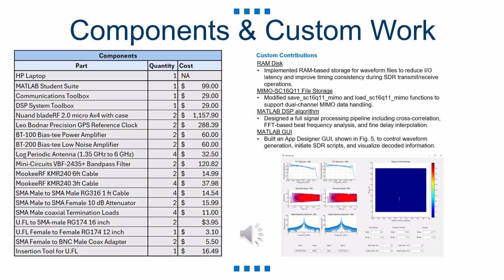The key contributions include the implementation of the RAM disk to store waveform files, which improved latency issues. I adapted the SC16Q11 storage functions that were provided by Nuand, who manufacture the BladeRF software-defined radio, and I modified them to